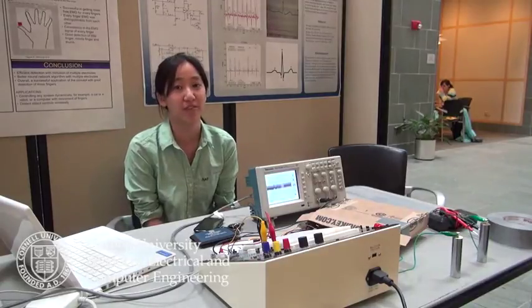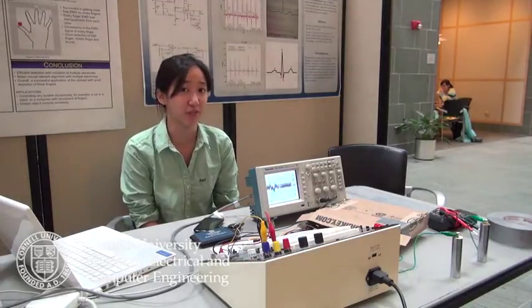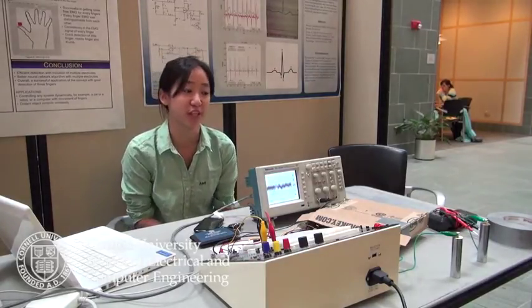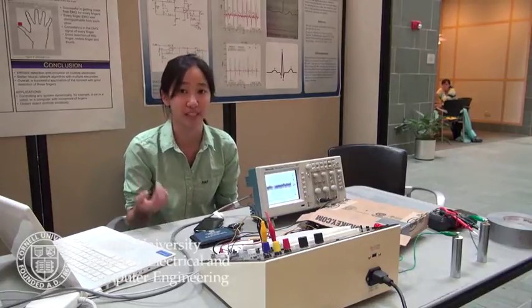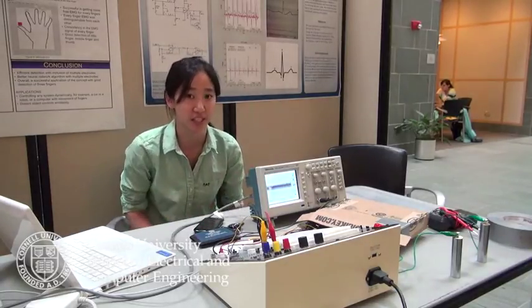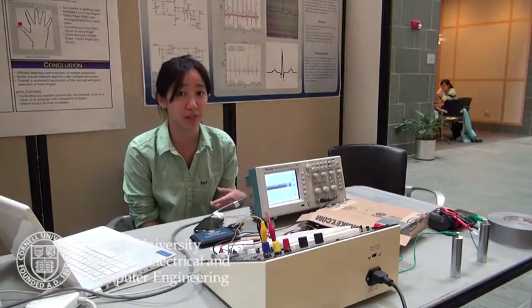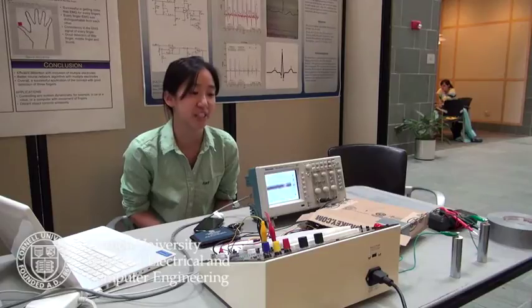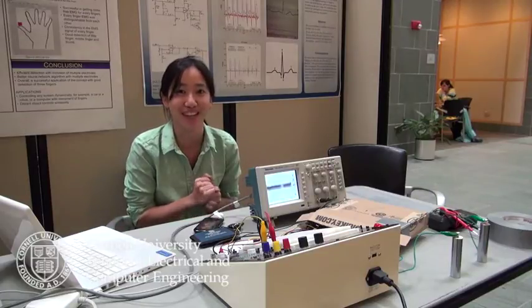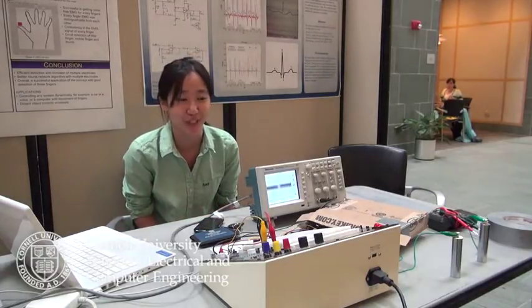Afterwards we have a gain stage with a differential amplifier, and then more filters and other gains to amplify the signal so it's stronger and we can detect it on the oscilloscope. After that we passed it into the NIDAC and then did some digital filtering, which unfortunately isn't here right now, just because we didn't have a computer to bring that had the licensing for the NIDAC materials.